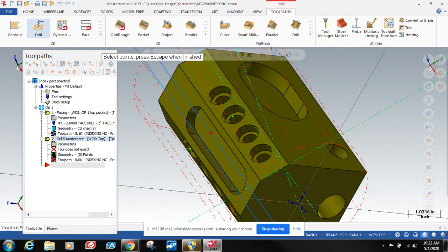So you had to set up your stock first. Remember, he was like 7 inches and then like 8 inches. I'm actually in it right now. If I go back to stock setup, it's 5 inches for the diameter, then I got 7 inches here. Then the coordinate is minus 7.0. So the shape is from a cylinder, the axis is X. Display fit screen, wireframe.